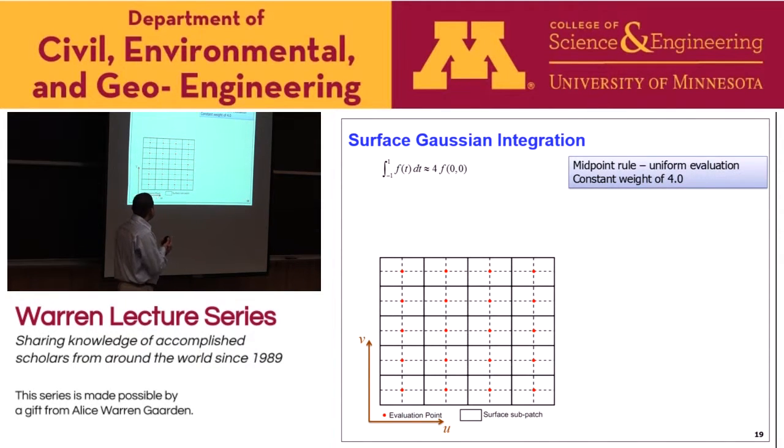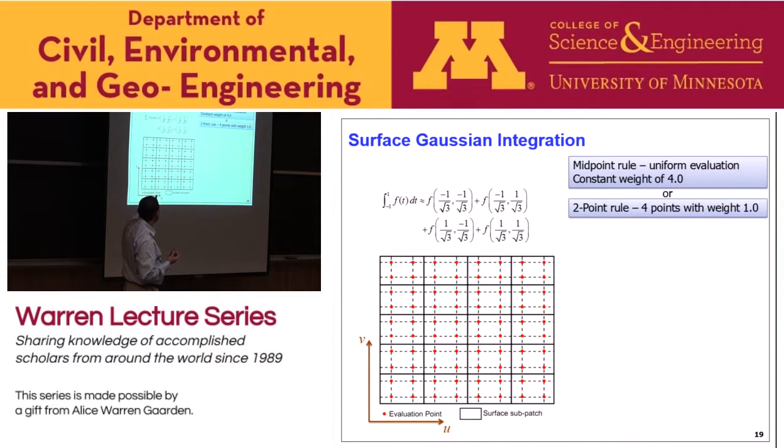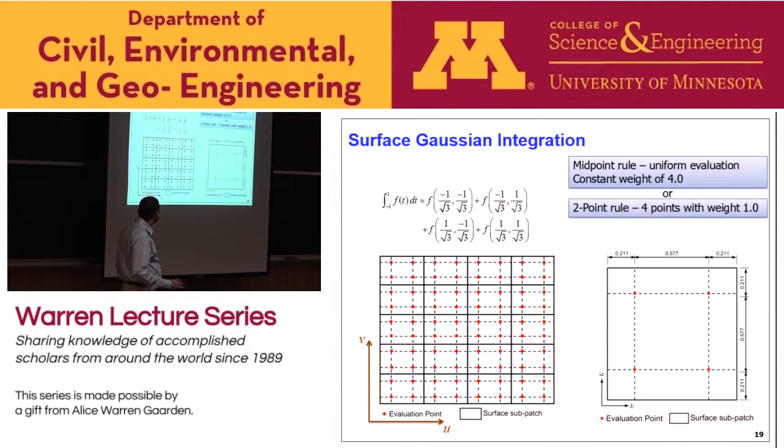For doing the integration, this is a recap of what happens in Gaussian schemes. That was 1-point integration, where each of those patches is a division of the whole NURBS patch itself, and then we perform 1-point, 2-point, or 3-point integrations on each of those patches.